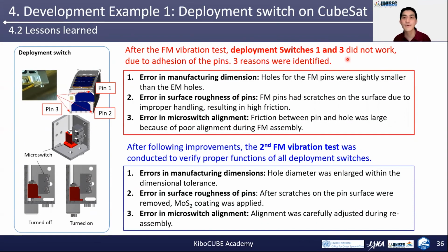After the flight model vibration test, our deployment detection switches 1 and 3 did not work due to the adhesion of pins. After investigation, 3 reasons were identified. First, the manufacturing dimension was not appropriate. The holes for flight model pins were slightly smaller than the engineering model's holes. Second, the surface roughness of the pins was not appropriate. The flight model pins had scratches on the surface due to improper handling, resulting in high friction.